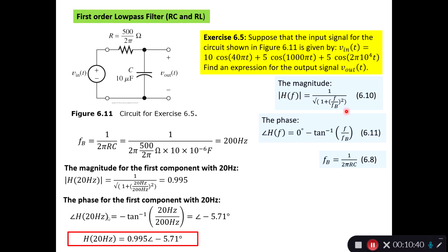I use this information in my equation, but I also need to find the frequency for the first component, and it's hiding inside here, because normally we have 2π times f times t that stands here. So I can see there's a 2 missing, so if I divide 40 by 2 I actually get 20 hertz. That's the first component frequency.